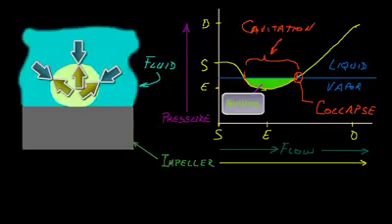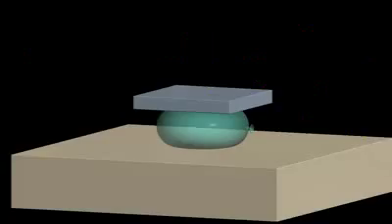During the process, the pressure of the fluid increases to the point that the gas bubble collapses rapidly under the increasing fluid pressure. This rapid collapse or implosion of the gas bubble is the cause of much of the damage that occurs during cavitation. Let's take a look at this short animation to help illustrate how this gas bubble collapse causes the damage that it does.